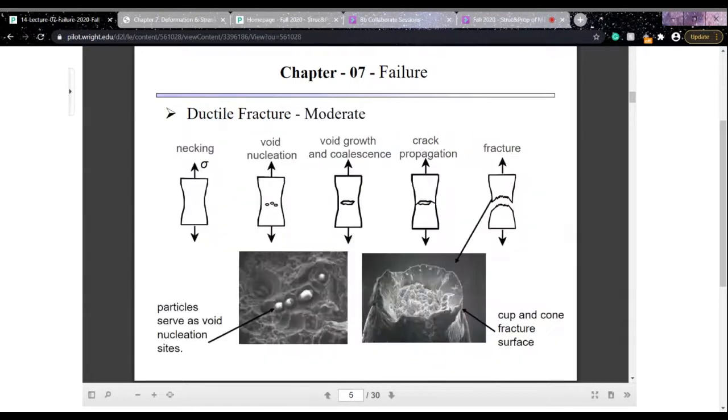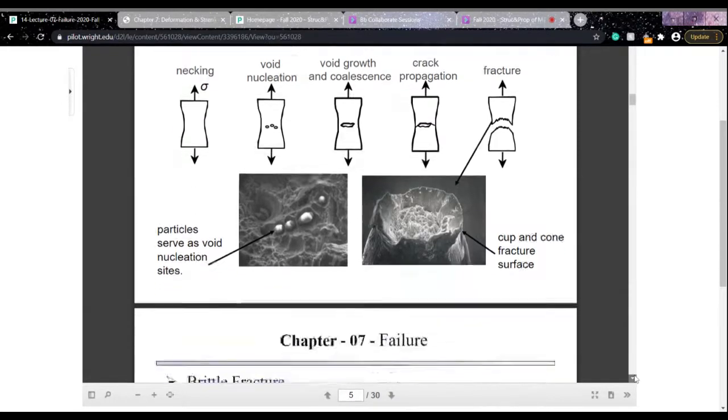of the force applied. In ductile fracture, first when a small crack is formed, these cracks combine with each other, their coalescence, and then after initiating the crack, it takes a certain time for the crack to propagate, and then the material undergoes a certain amount of deformation, and then the material undergoes fracture. And this is the cup and cone surface for a ductile material.